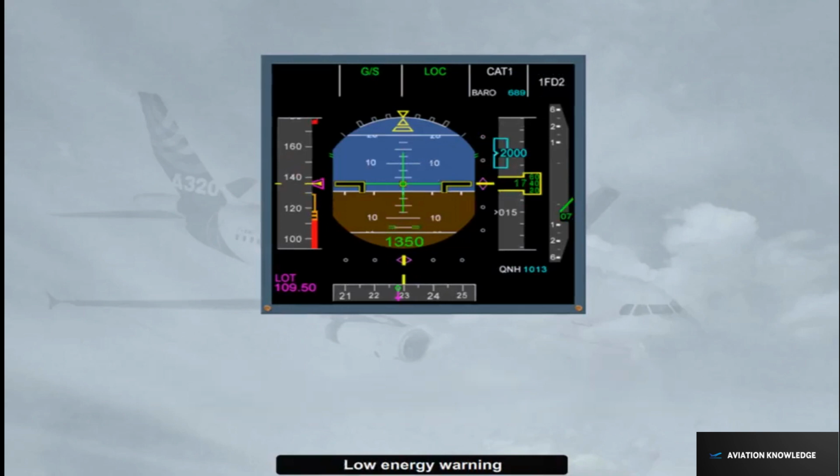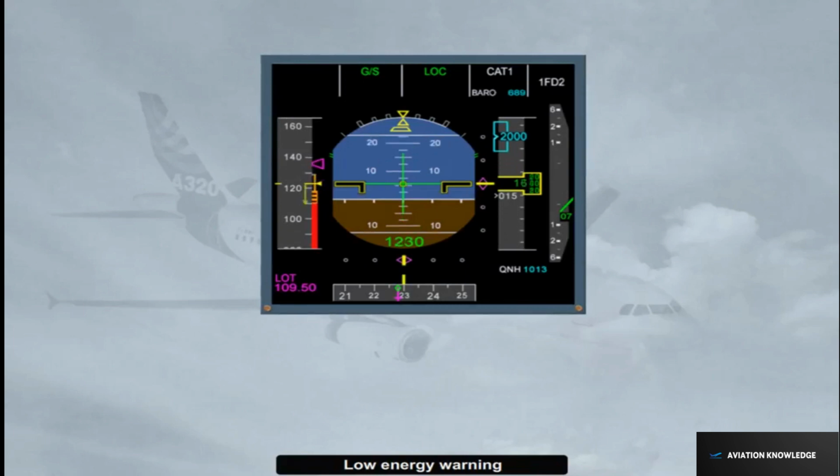If, for any reason such as turbulence, shear, auto thrust off, the airspeed drops significantly below VLS, an aural warning, "speed, speed, speed", is automatically triggered by the FAC and is repeated every 5 seconds. It drives pilot's eyes to the speed scale so as to manually increase the thrust and in order to regain a positive flight path angle through the pitch control.